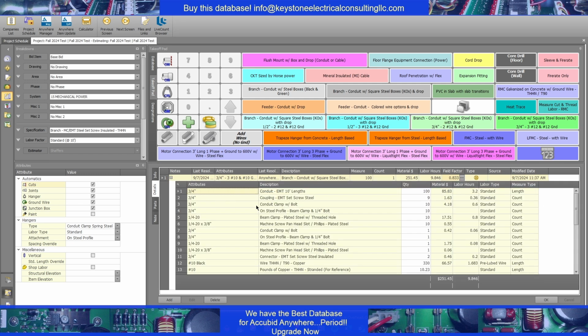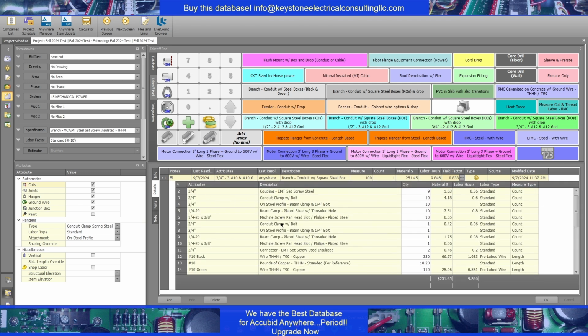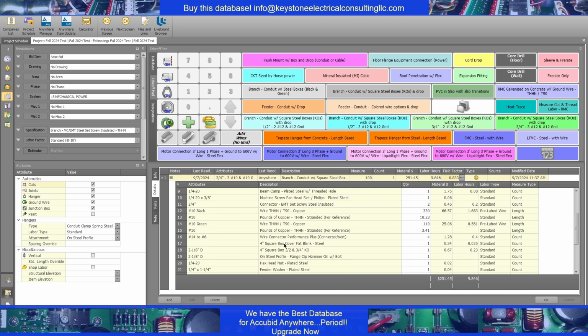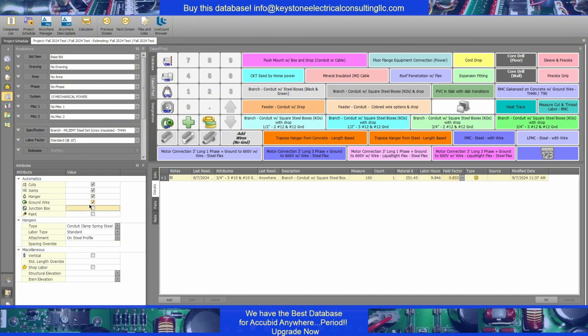If I drop this down, you'll see there's my EMT. I've got all my correct stuff there. I've got a junction box here. Now, if I didn't want that, I could uncheck this junction box icon over here, and I might do that for that example. And I would always do it while I see the OK and cancel in this edit mode. I wouldn't have done this before I entered this. So that's kind of a technique too. The reason for that is because then once I hit OK, then this box will go back on. And that's kind of the technique there.